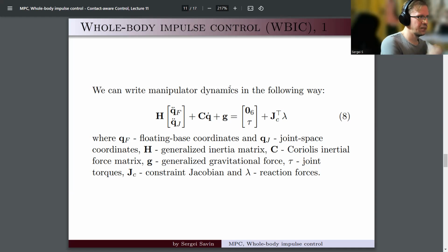The difference between basic inverse kinematics and what the original writers of the paper propose is that they wanted to prioritize certain tasks over others, so that the inverse kinematics is solved exactly for some tasks and inexactly for others, all at the same time. The inverses are taken not to minimize least squares, but to minimize some inertially weighted least squares. Okay, so that is the idea.